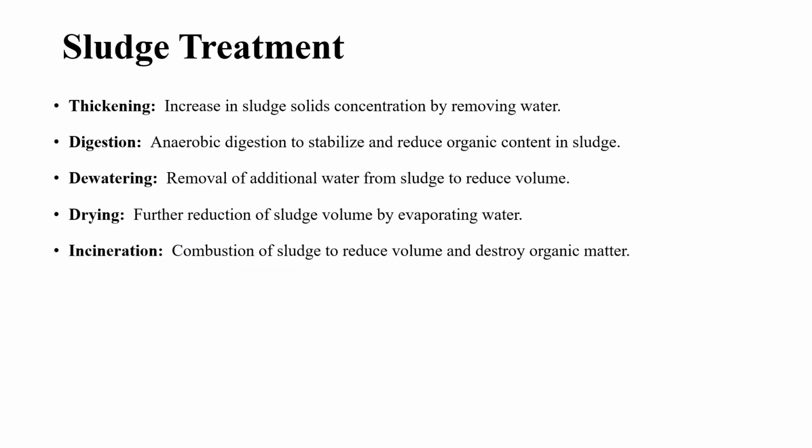Finally, there will be sludge treatment. In wastewater treatment, we may think there is no waste from water treatment plants, but actually there is a waste, that is sludge. We can remove the sludge by using different procedures. The first is thickening the sludge. Thickening helps us use the sludge for construction materials or digestion.